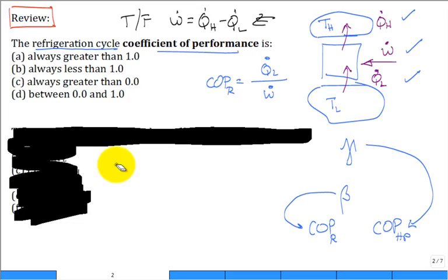All right, we're going to get to some refrigeration systems which are not really all that efficient. That's later in the textbook, but they'll have low COPs. They may have a COP of 0.5, meaning that if I want 1 kilowatt of cooling, guess how many kilowatts of power I have to supply? 2 kilowatts, doesn't it? Which means I've got to dump 3 kilowatts of heat to the environment somewhere. That's not a very efficient system, but yes, you can have it.